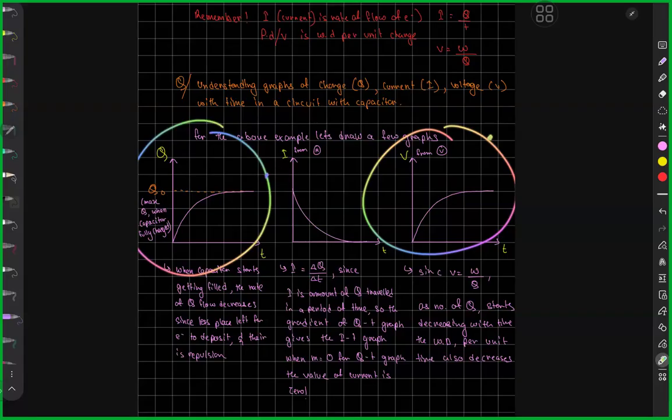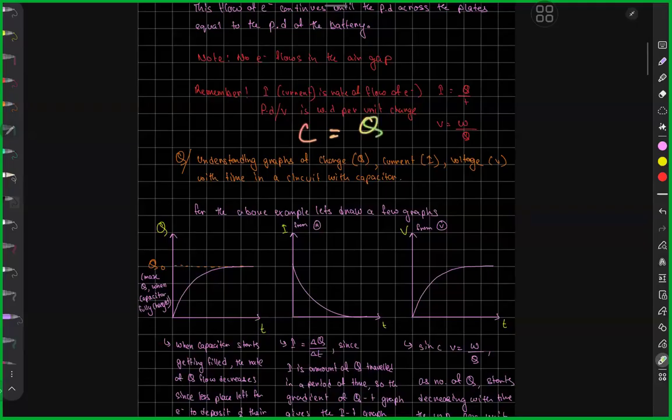But the point I'm trying to make is, let's say the supplied voltage increases from 12 volt to 13 volt to 14 volt. What would happen in the capacitor? Wouldn't more charge be stored? Yes, definitely, and in exact proportion, because C equals Q by V. As charge accumulation increases, voltage across increases as well.